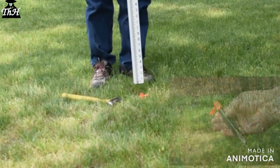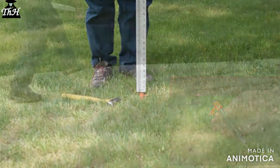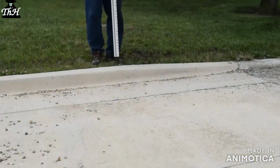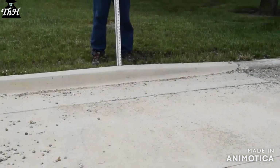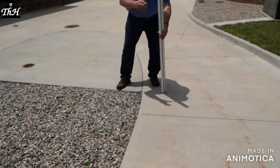Here, the rod person is using a cold chisel driven firmly in the ground. When it is stable, its top can have only one elevation. This concrete curb has high spots that make good turning points. And this sidewalk corner will work too.